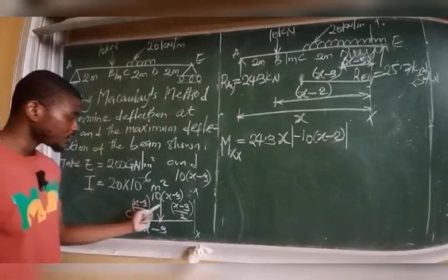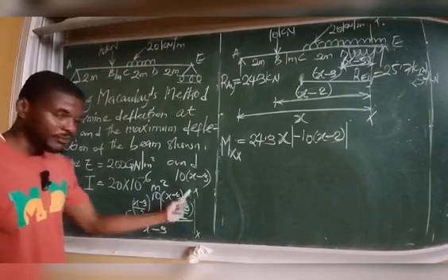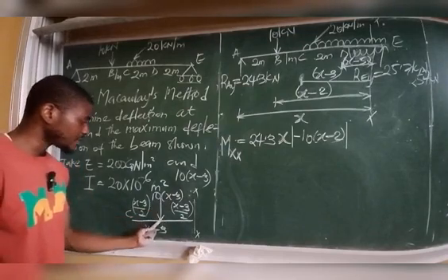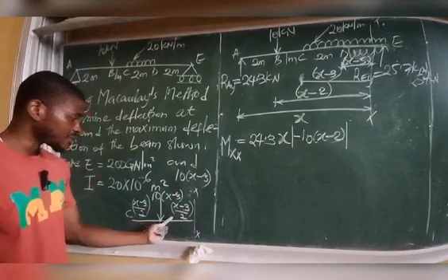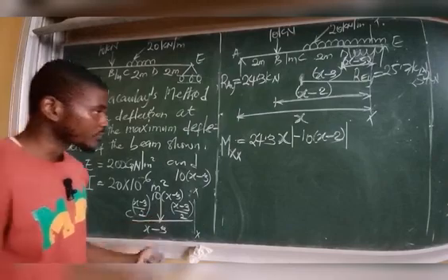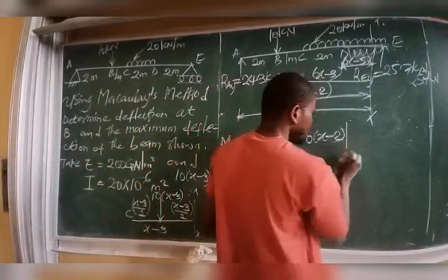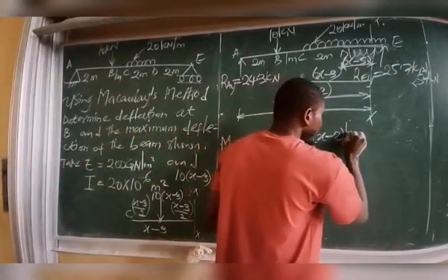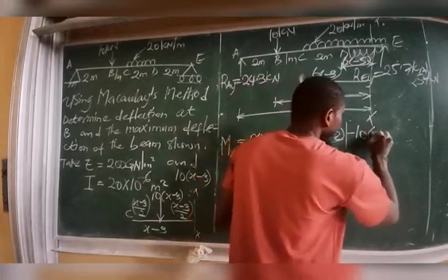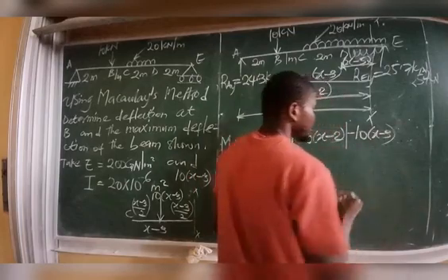So the moment of this load 10 into x minus 3 about the point of section becomes 10 into x minus 3 times the total distance it takes to get to the point of section, and that distance remains x minus 3 all over 2. Alright, so the moment of this force is now equal to, first of all, it is acting downward, so it's negative. So I simply have minus 10. Converting this first to a point load, simply multiply by x minus 3. This is the load.